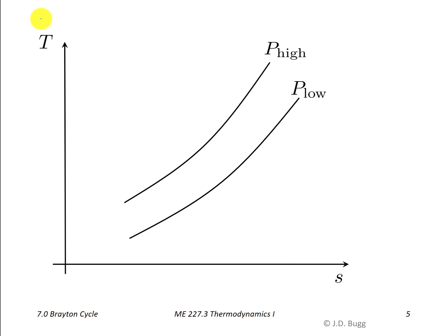Now the cycle itself, we're beginning with an ideal cycle. And remember, an ideal refrigeration system and an ideal Rankine cycle meant that the compressors and turbines were all 100% efficient. Well, it means the same thing here. So an ideal Brayton cycle will have an isentropic compressor and an isentropic turbine. So the isentropic compressor is a vertical line going from low pressure, so that's point 1, up to point 2. So that's the first of the 4 processes in our standard Brayton cycle.